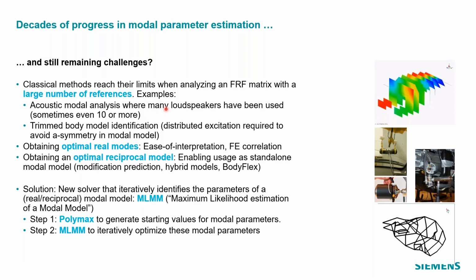But for acoustic modal analysis, you have to use a lot of loudspeaker locations, sometimes even 10 or more, to get a nice excitation of your entire cavity of the car, for instance. That caused some problems in curve fitting this data. The same is true for trim bodies, so highly damped car bodies. Also there, we need to apply a lot of excitation points to get a decent modal model. That was some of the reasons why we developed a new method called MLMM.